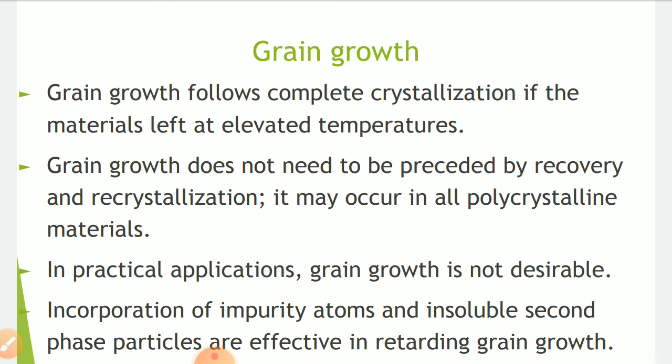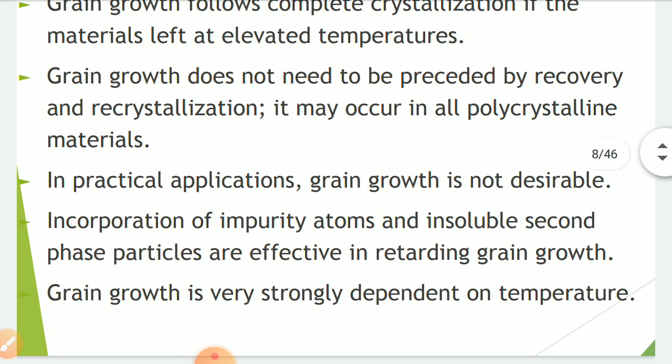Generally the process is recovery, then recrystallization, and then grain growth. But as the second line mentioned, it does not need to be preceded by the recovery and recrystallization. Remember this one, it's not at all necessary. Directly grain growth can take place if we leave the material at elevated temperature. In practical applications, grain growth is not desirable.